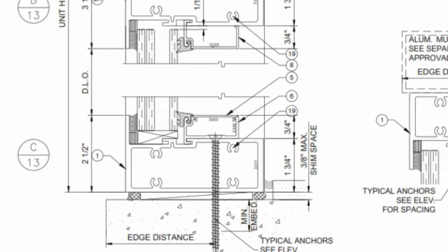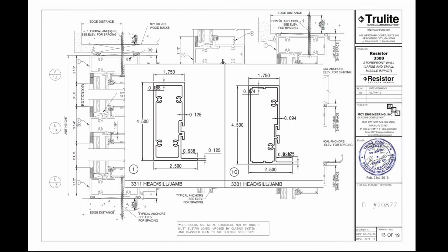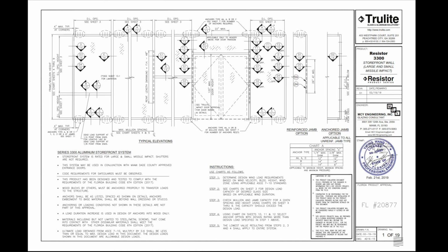And that frame element has 4 screw spline screws. So there are different frame members being used at the sill, which is totally fine because they're both called out and they're both included in the approved product instructions. So these are both valid to be used. That's why you have so many different details here that appear to call out the same part of the frame. Really, they're calling out different profiles and different options that can be used in different cases.